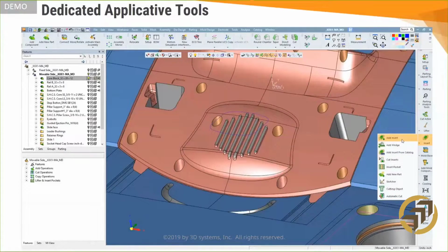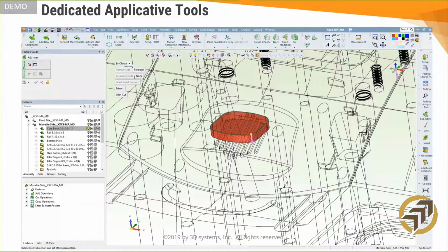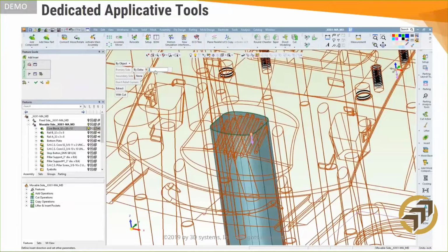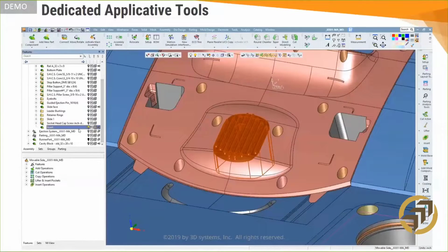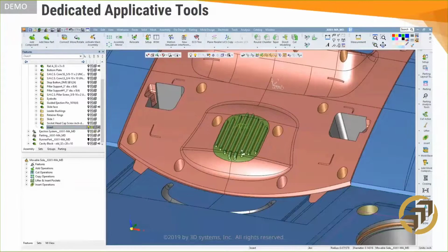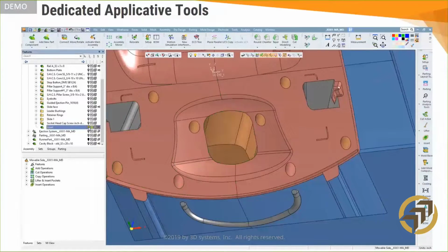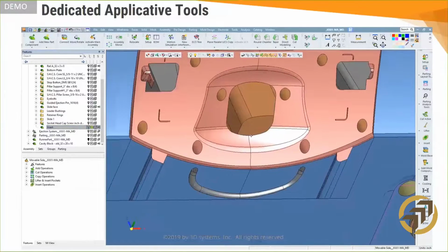This unique approach to design for tooling continues into the more specific functions built just for molds. Mold inserts are a common need, so whether the situation calls for a simple core pin or a custom shape, an insert design tool is available to help. Inside these tools are options for clearances, tapers, or wedge shapes to anchor the insert in place. After cutting its own pocket, the finished insert remains fully associative to the original plastic part.